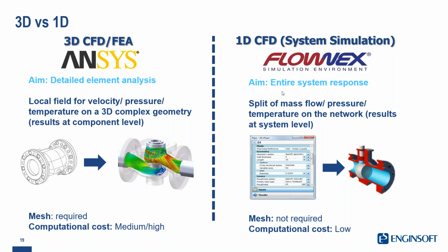So the idea is to start from the 3D analysis and find a way not only to transfer the information, so not only some performance curves, but complex parameters in a surface of response, and to transfer the surface of response into a 1D component.